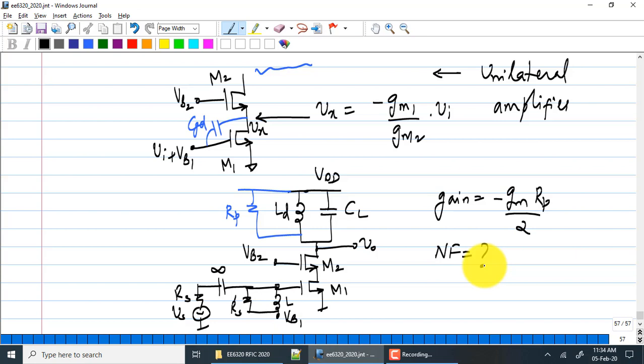Not much larger than 1. Okay. 1.5. First thing I can tell you, let us assume that the transistors were noiseless. Let us assume that the cascode doesn't add any noise anyways. Right? That is for sure. All of you are taking analog ICs also, I think. You know that unless there was capacitance at this node, the cascode will not add a lot of noise.